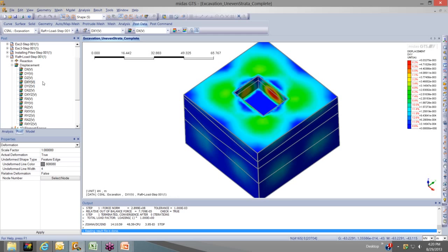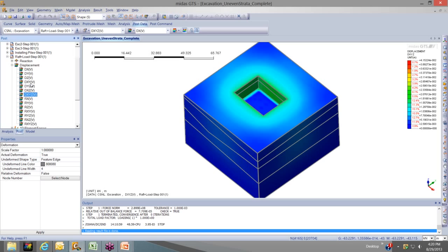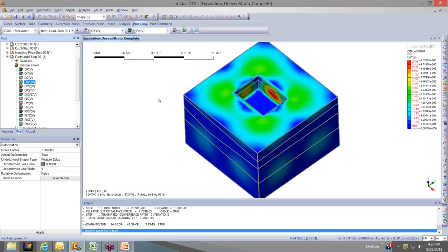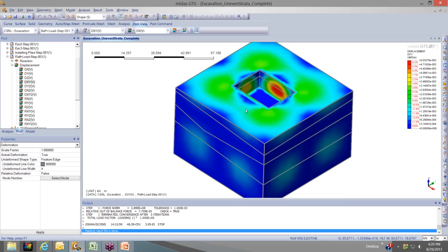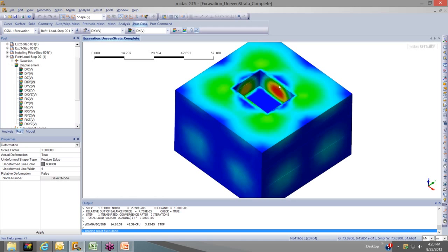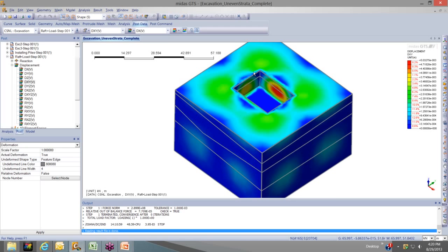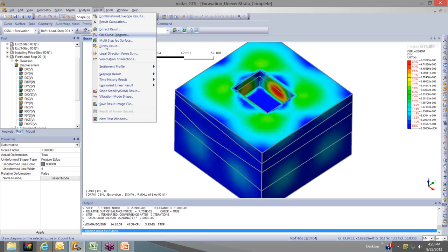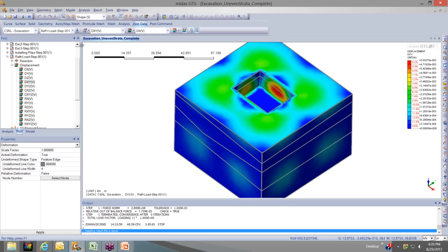Okay, so let's go to your displacement in the XY plane, or maybe in 3 dimensions. Let's stick here. Okay, so say you have this particular contour model is of interest to you for whatever reason, but you want to find out maybe the minimum or the maximum values. So what you would do is you'd go to Results, and then you'd select Probe Result, this icon here.